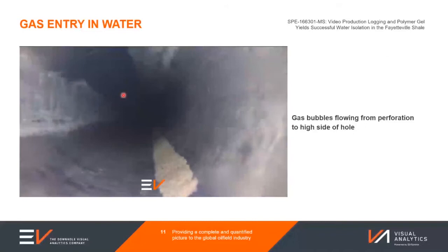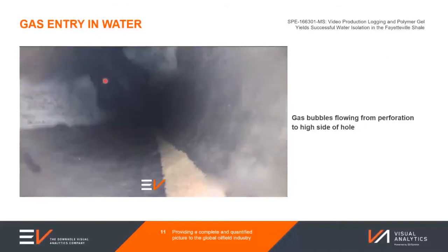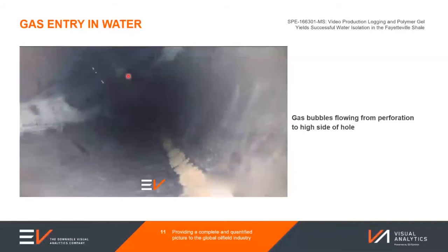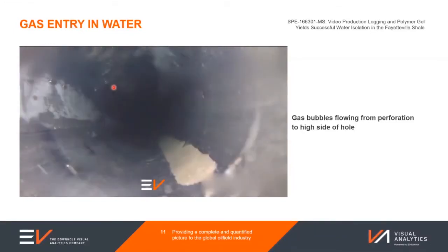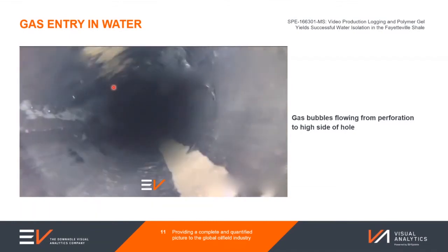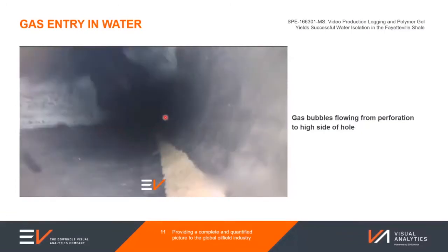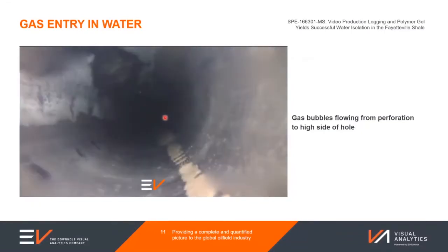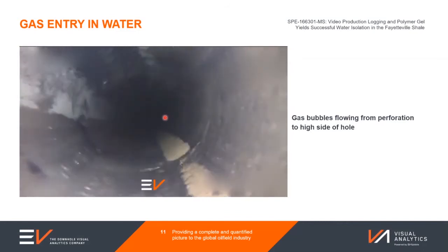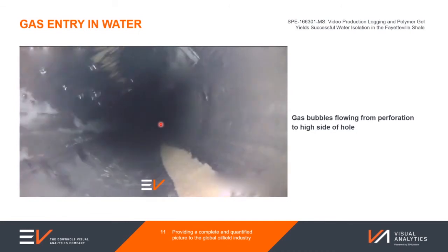And in a lot of instances, a centerline production logging tool would really fail to understand the presence of the gas flowing on the high side as well. It's just dominated by the surrounding water. But the video provided clear evidence that although there's a lot of standing water in this zone, there are still hydrocarbon-bearing areas, and we wanted to protect those and not unduly isolate this from the production stream.